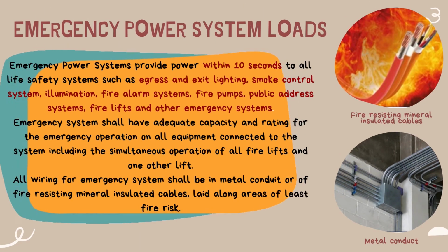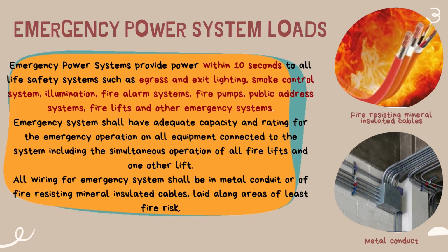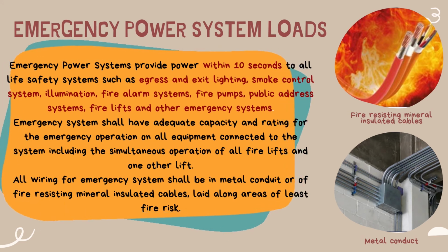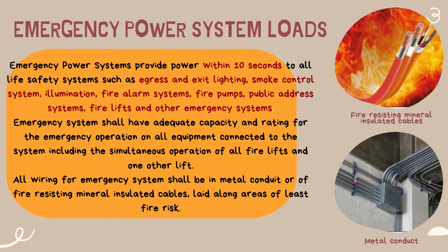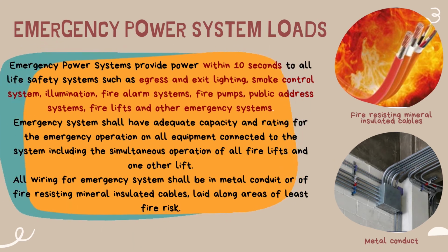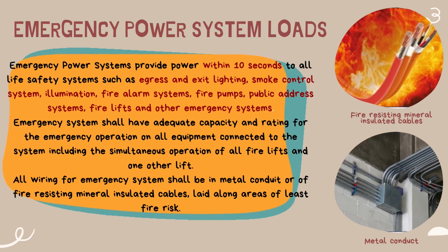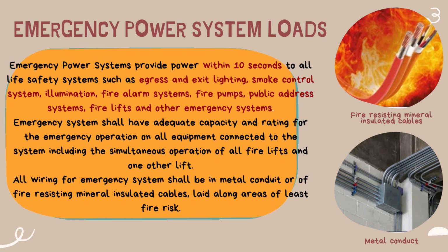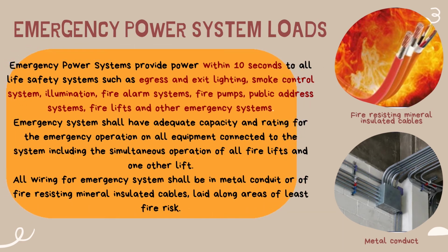For the emergency power system loads, it provides power within 10 seconds to all life safety systems such as exit lighting, smoke control system, illumination, fire alarm systems, fire pumps, public address systems, fire lifts and other emergency systems. So we can conclude that it takes only 10 seconds to activate all the equipment or systems linked with the emergency power system.